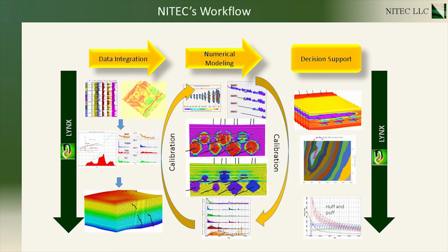Subsequent to the incorporation of the geological, petrophysical, geophysical, and well history data into the model, the process of history match calibration begins. The primary focus of the NITEC approach to history matching is the calibration of the hydraulic fracturing response of the reservoir system. Hydraulic fracturing is simulated stage by stage, utilizing the historical injected fluid volumes. The 6X reservoir simulator captures the dynamics of rock breaking via tensile and shear deformation, and provides options for proppant transport simulation.